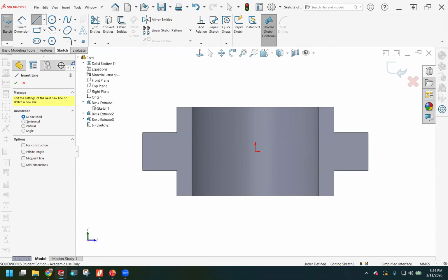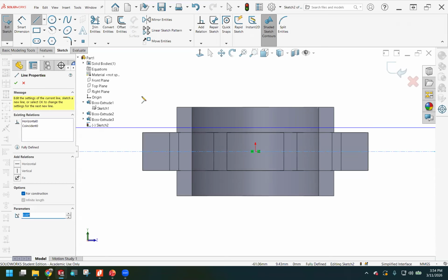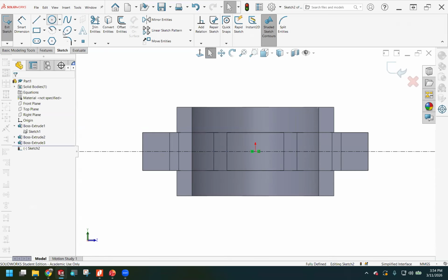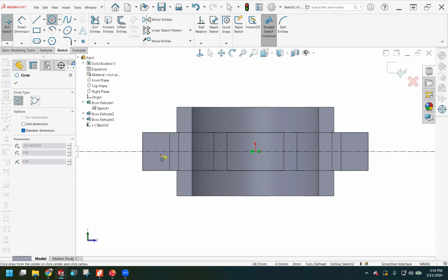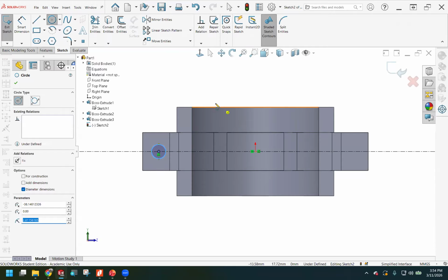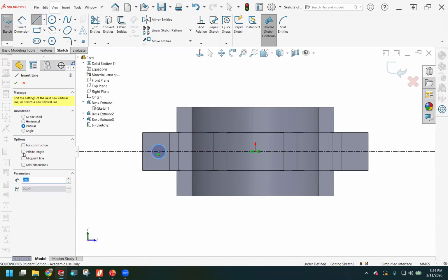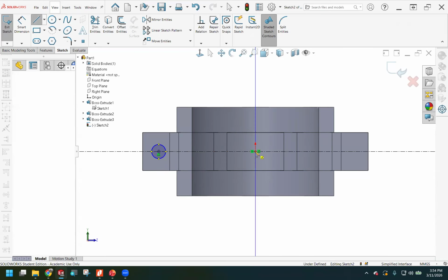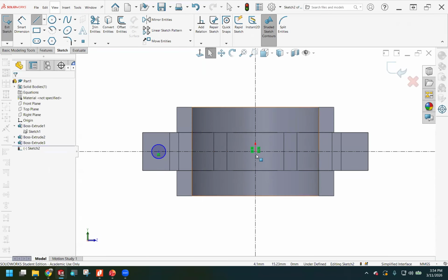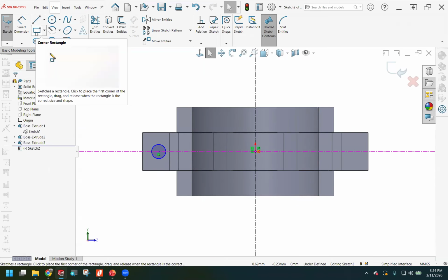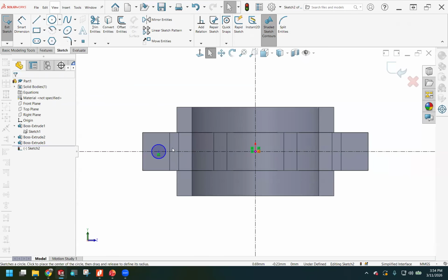As usual, we're going to start by creating a sketch line to work from. And then we're going to create, I know I need 2 circles here. And for that matter, I'm going to create a second vertical construction line so that I've got a nice mirror to work from. Both of them snapped to my origin. And then we also need another circle on the top over our whole circle.